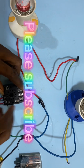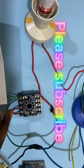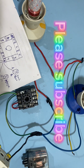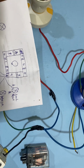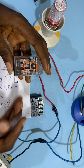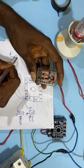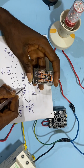The next thing after connecting all the neutrals together is to connect my live supply from the generator. This is my live supply from the generator. I'm going to connect it to pin 11 of the relay. So this is pin 11 of the relay, and this is my live from the generator to pin 11. All right, I'm done with that.